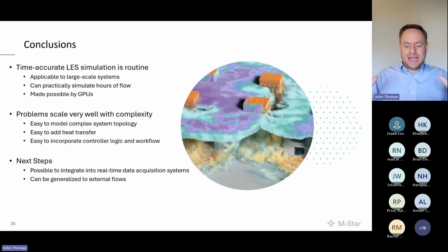And this is really an incredible view where you can see how the timescales of the eddies interact with the timescale of the flow rate of the vent, interact with the purging timescale or the residence time of the fluid, interact with the PID controller timescale to produce some sort of aggregate system performance.